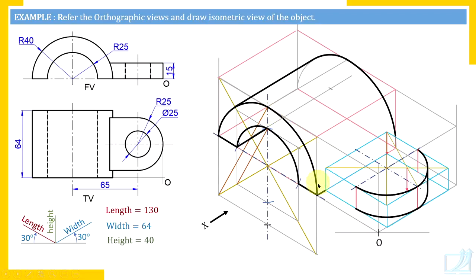Identical curve, watch here, this longer arc, we are going to draw at a distance of 7 millimeters because that joint is at a distance of 7 millimeters. So how to shift this curve 7 millimeters? Simple. Check where the center of this bigger arc is. It is here. Now move that center 7 millimeters.